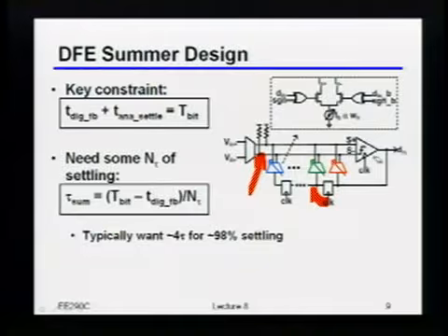Okay, so that's actually a very important point, which is one of the subtleties, but really beauties, of this structure: in terms of the current, I'm really adding all the currents linearly. So the subtraction I want to do in terms of the signal processing is correct. The only thing is that afterwards, I'm going to distort it through some nonlinear impedance at that node, which means your voltage amplitude could be smaller, right? For those signals with relatively small voltage margins, you could make an error. So you are right that if the nonlinear impedance of that node is sufficiently low compared to your load resistance that you basically don't get the amplitude you want, then that indeed would be a problem.